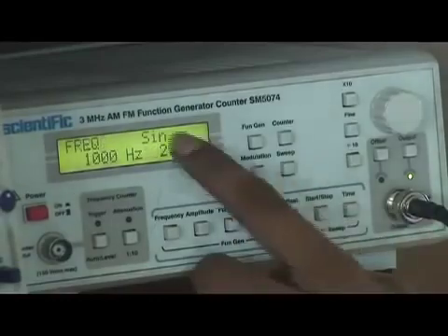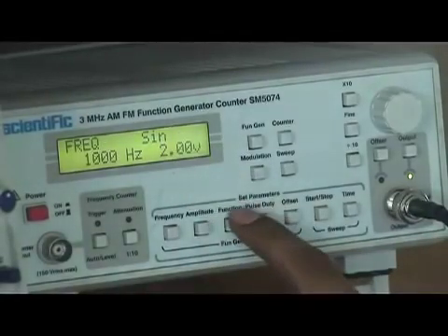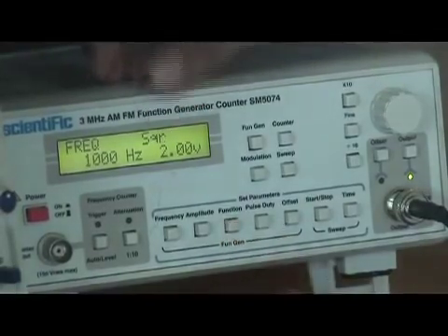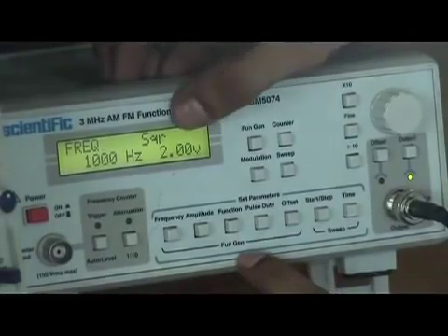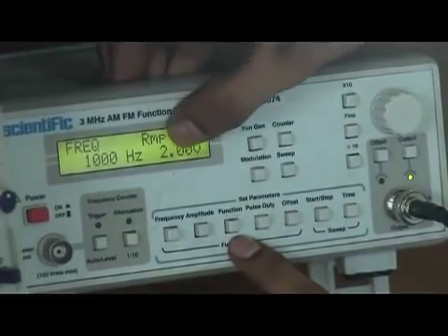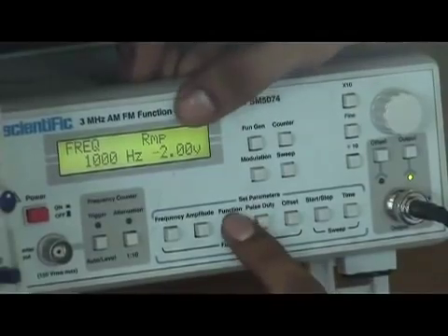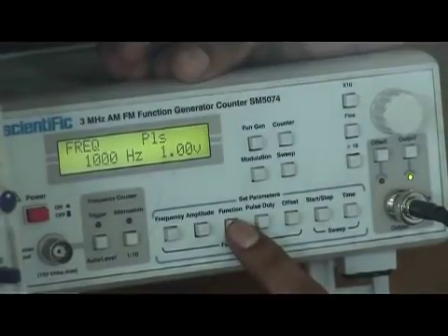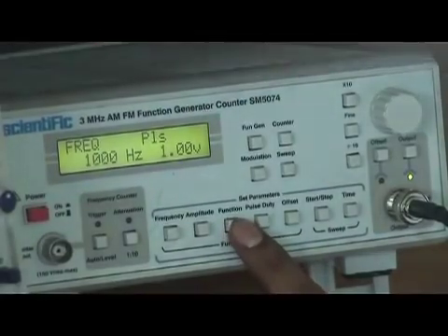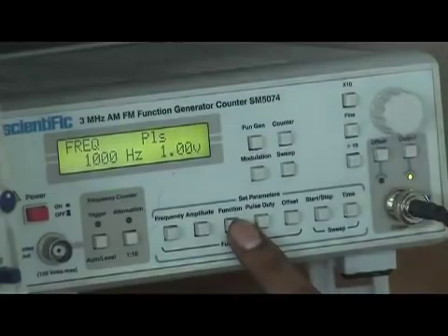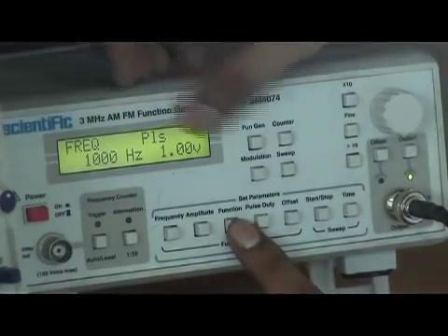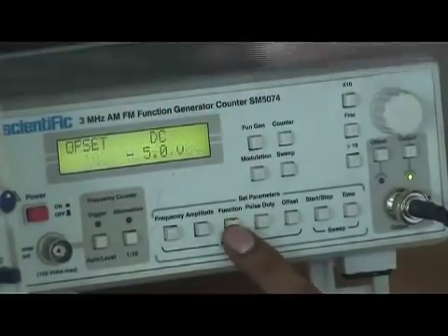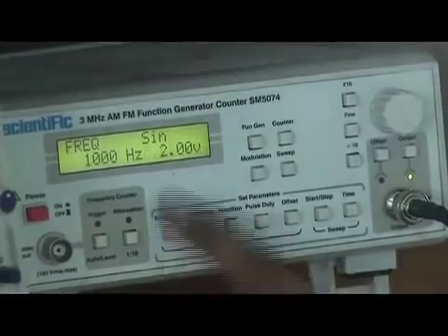Now what is the function? My function is sinusoidal. You can change the function from sinusoidal to various functions like triangular. If you press it again, square. Ramp, it's 2 volt. Ramp minus 2 volt means a negative ramp. This is pulse 1 volt, because when we say pulse, it denotes only from reference to the upper level, or reference to the below level. When I press it again, it says a pulse for minus 1 volt, means below. Then a DC voltage, then again back to the sinusoid.